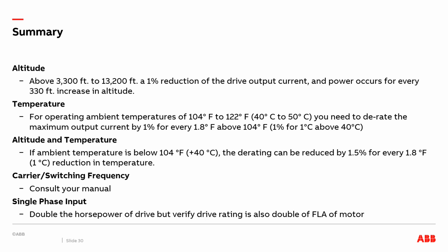In wrapping up, we talked about single-phase input, and when we have this type of application, double the horsepower of the drive, but verify the drive's rating is also double the FLA of the motor.